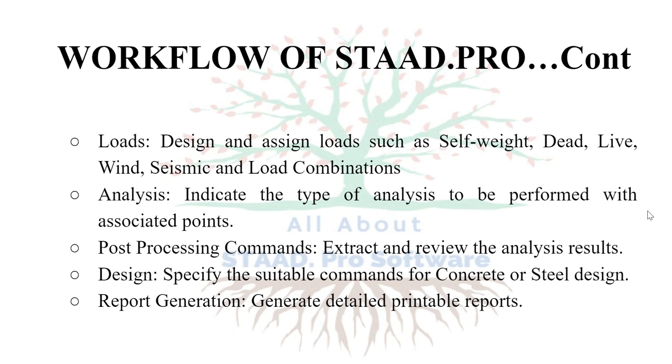Sixth one is loads. Define and assign loads such as self weight, dead, live, wind, seismic and load combinations. The type of load you are going to provide should be specified. Seventh one is analysis. Indicate the type of analysis to be performed with associated commands. What type of analysis is to be carried out should be specified. Eighth one is post-processing commands. Extract and review the analysis results. We can see the analysis results and review or extract them through post-processing commands.